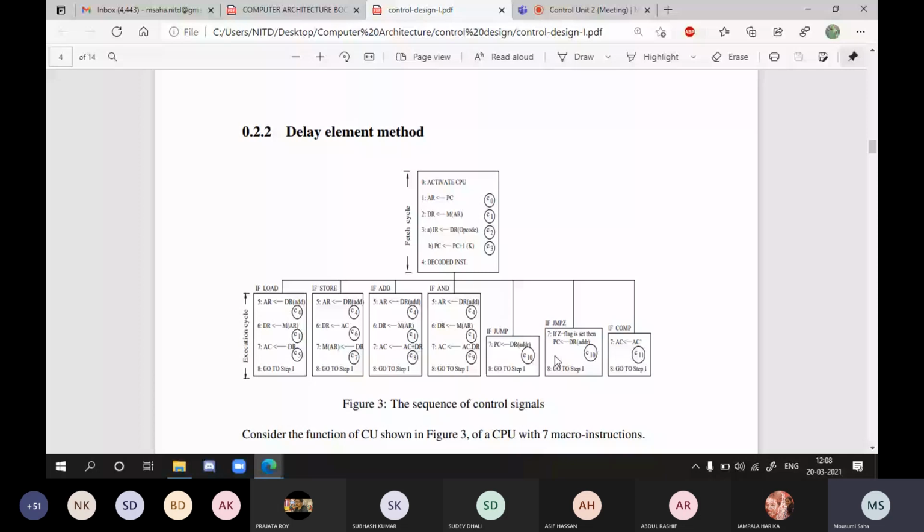For each instruction, the opcode is stored in memory. So the processor has to read that opcode from memory and store it into the instruction register. This process is known as the fetch operation. And the time required is called the fetch cycle.